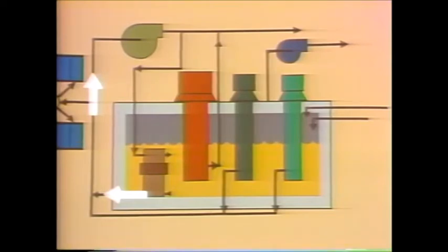Oil pressure is increased in the main lube oil pump so that it can be used to operate the control system. Once the oil has passed through the control system, it is returned to the reservoir to be used again. This overall system is usually called the turbine lube oil system. It, too, is a closed loop.